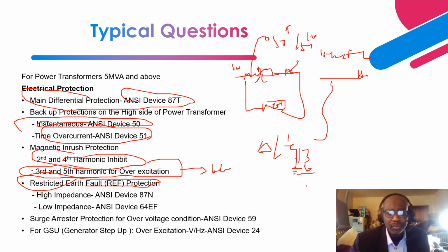At the neutral of the transformer, the differential protection cannot cover the 5 to 10% area near the neutral. When there's a ground fault here, there won't be enough differential current for the differential relay to detect a fault in the last 5 to 10% of the neutral region of the Y-wound transformer.